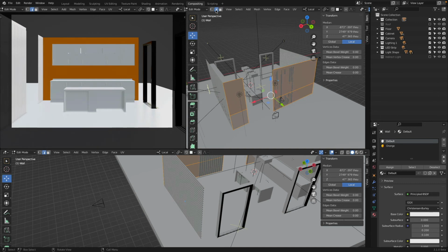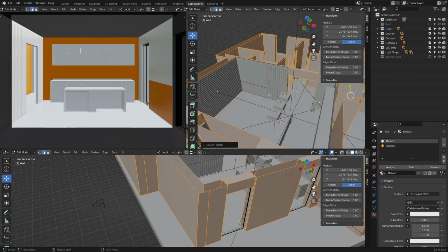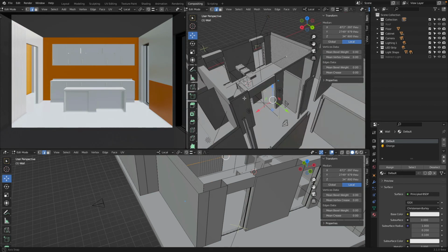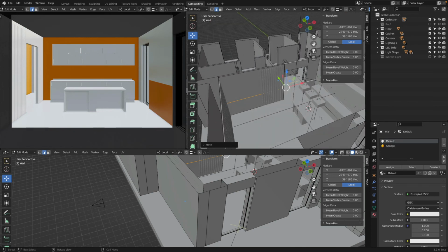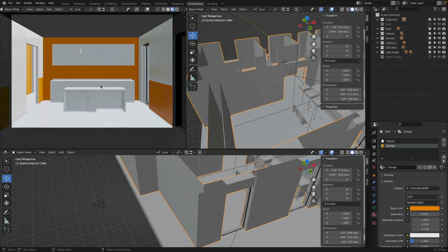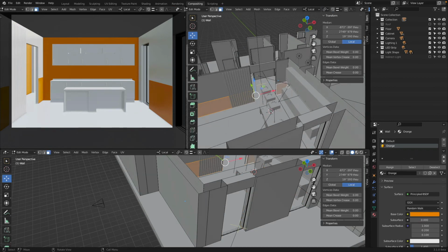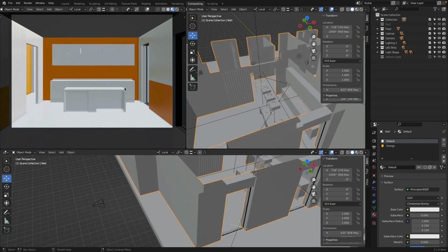Go to this edge select and edge snap. Click this, move this, and now I hold Control and move my cursor right over this edge, and you see how this snaps to it. Alt-H, and then I can select this edge and this edge, move this up, hold Control, snap to this edge. Now they're all lined up perfectly. Select both faces, assign. There we are. Look at that. We don't like this design. Well, no big problem. We can always select them, select the other material, and bring this back.